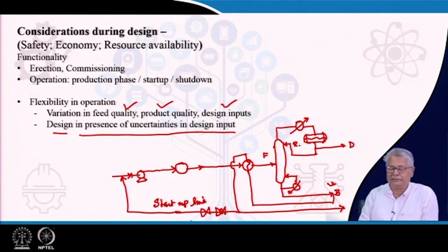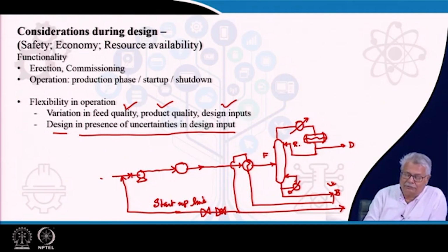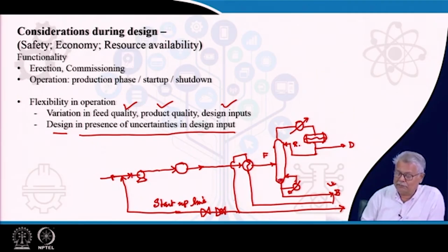So, what happens is when you start your feed, nothing vaporizes. So, it comes here. The entire thing is again drawn from the bottom and is sent here. So, what you actually will be having here is one more pump which will be like this. This pump will be started once you have sufficient level here. It sends the entire thing back to the feed line, which keeps on circulating.